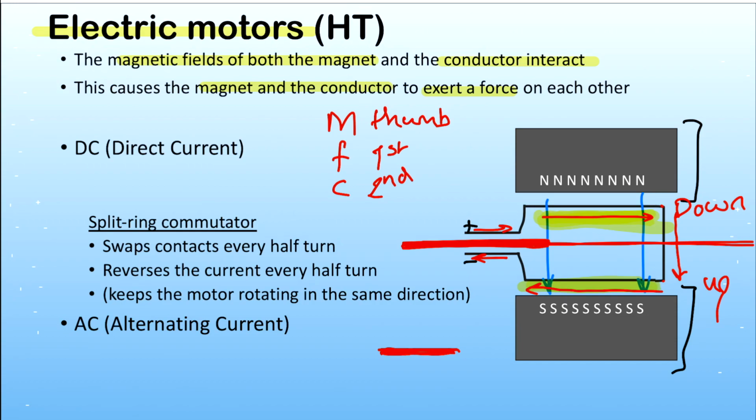The left side is going to go down, and this side is going to go up. So it's going to rotate around to this position, and eventually it's going to rotate around to this position until it's vertical. Now if you've got a direct current running through all of these wires, that's going to end up making it just stay in a vertical position, because that's at balance. The bottom's no longer going to want to move any further around, the top's not going to want to move any further around, and it would stay put, and that would make a pretty useless motor.